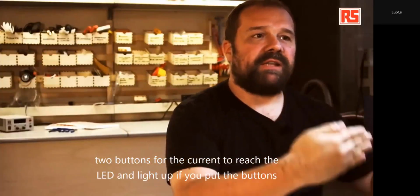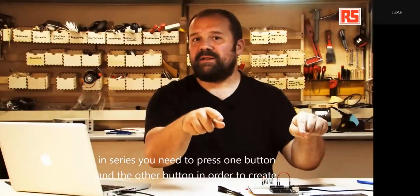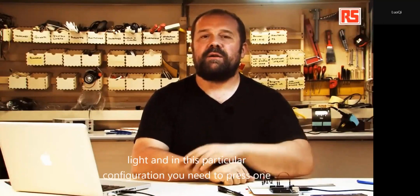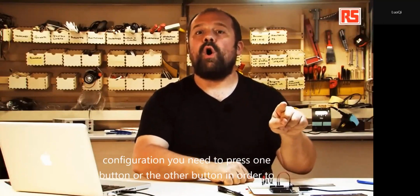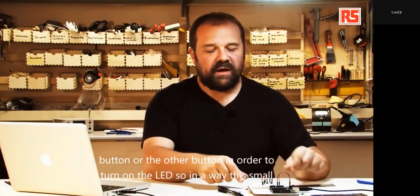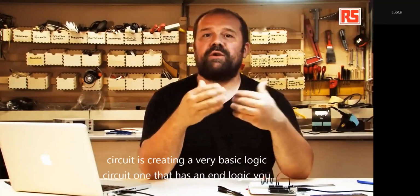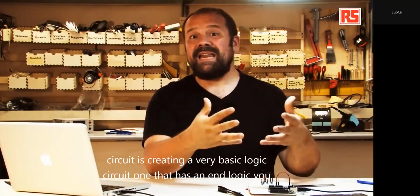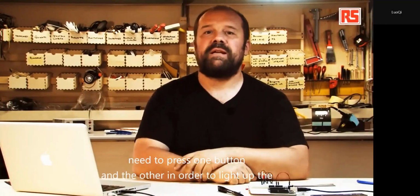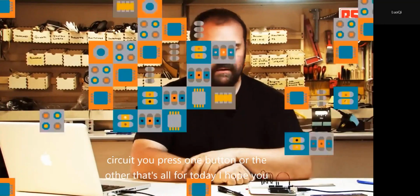If you put the buttons in series, you need to press one button and the other button in order to create light. And in this particular configuration, you need to press one button or the other button in order to turn on the LED. So in a way, this small circuit is creating a very basic logic circuit. One that has an AND logic. You need to press one button and the other in order to light up the LED. And the second one is an OR circuit. You press one button or the other.